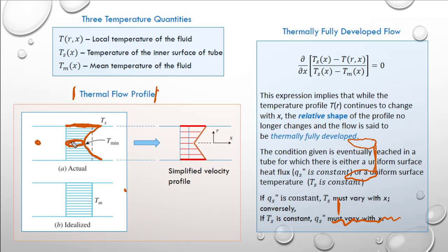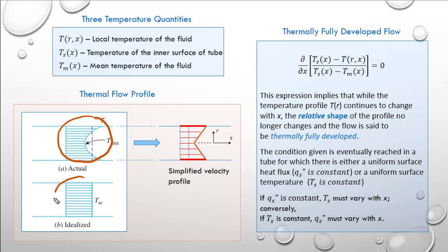the interior of the pipe near the center line is going to be at a temperature lower than the surface temperature. And then as you move further out towards the wall, the liquid is going to get warmer and eventually be at the same temperature as the surface temperature for the fluid that is right next to the wall. And you can take this and create an average, and we would refer to that as the mean temperature.